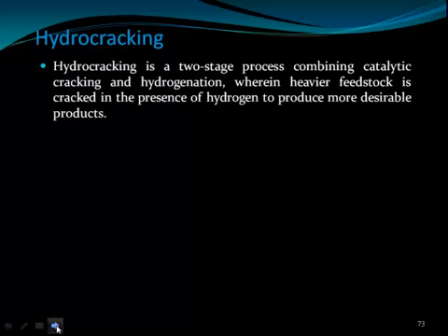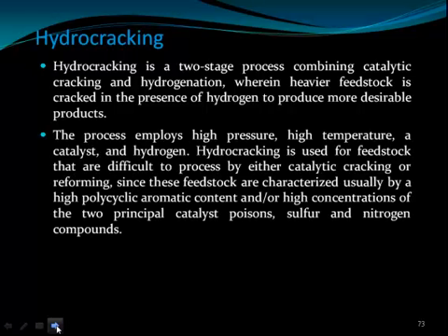So after hydrotreating, hydrocracking takes place, where we can crack the higher molecules into lower molecules. It is a two-stage process, combined catalytic cracking and hydrogenation, wherein the feedstock is cracked in the presence of hydrogen to produce more desirable products. The process employs high pressure, high temperature, catalyst and hydrogen.